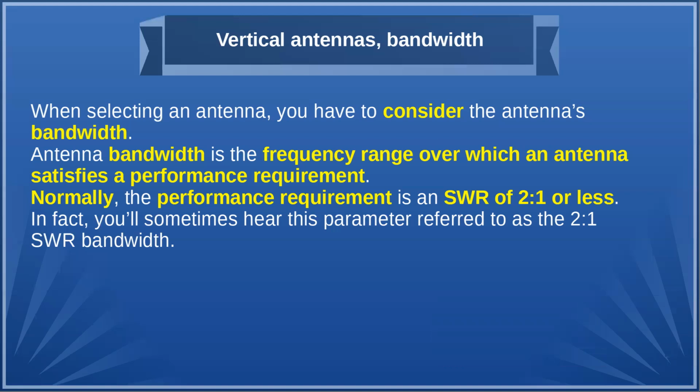I basically made my car antenna. I took a 102-inch whip with a homemade coil, got up to about 31 feet, and just put an SGC matching unit right at the bottom. So I could do 80 meters, no problem. I'd be on a dive trip, going down south, talking to someone in South America or something like that.